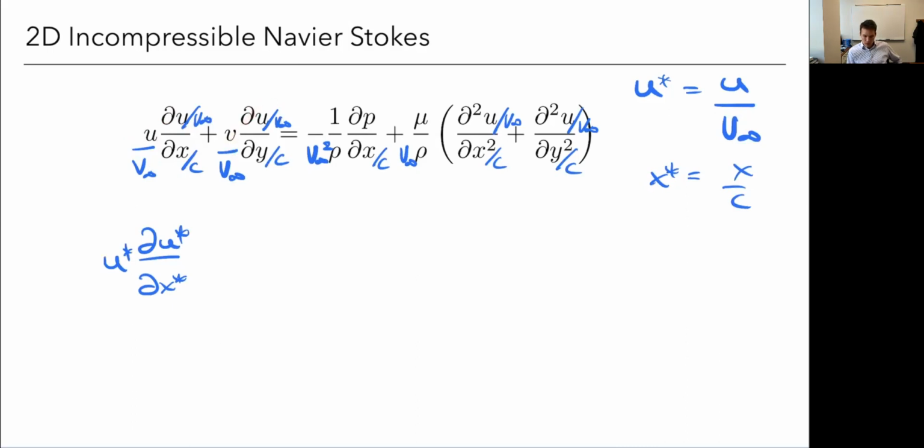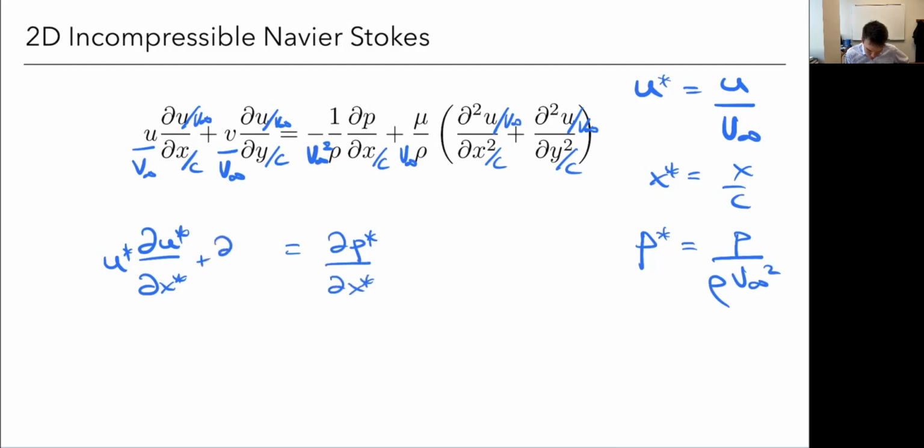So this one is also non-dimensional. Pressure divided by rho v squared. That's like a dynamic pressure. So we could define a non-dimensional pressure that way. There are generally better ways, but just for simplicity, let's just do that. That'll be my non-dimensional pressure. So then this term becomes P star over X star. And this is already V star times du star dy star.